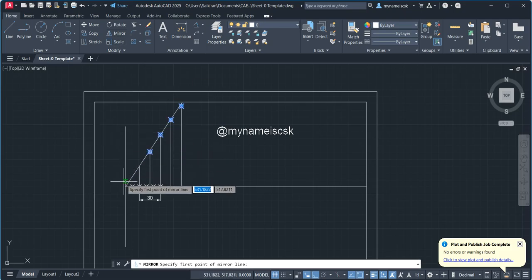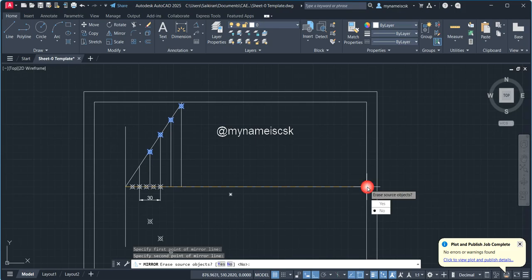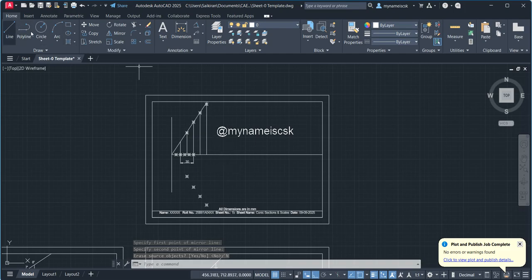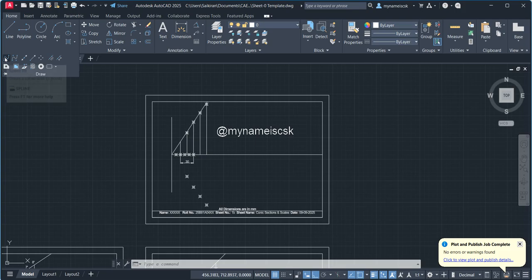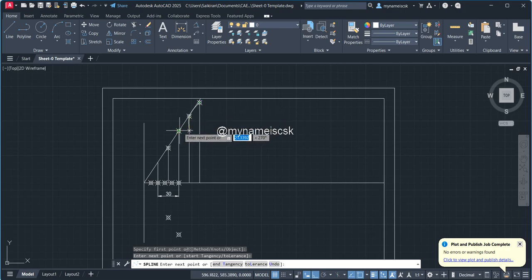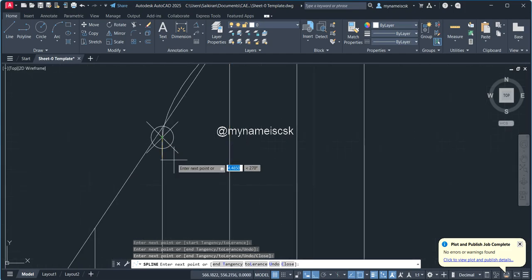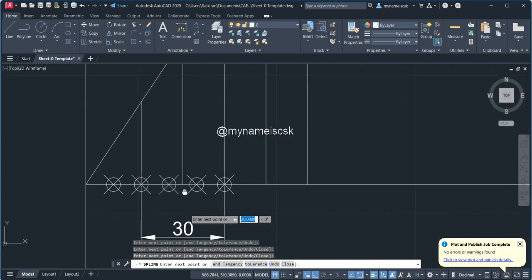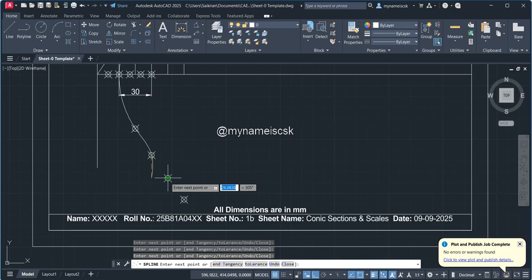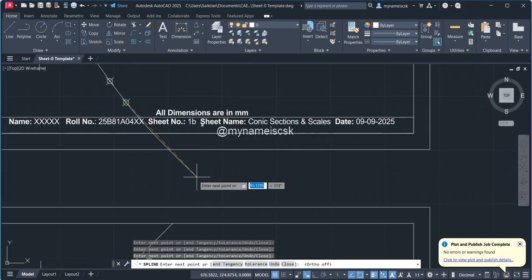I have to make sure that these points are also below the axis line. I'll use a command called mirror. I'll select this object here and here. So object and click on no, so that automatically it will be generated from top to bottom. Then I'll use a command called spline fit. So directly click on spline fit, select the top 1, 2, 3, 4, select the point correctly, then vertex you have to select correctly, then these points, you have to select these points. Okay, then you are closing it. So of the ortho, make sure that it is passing through this one and click enter.